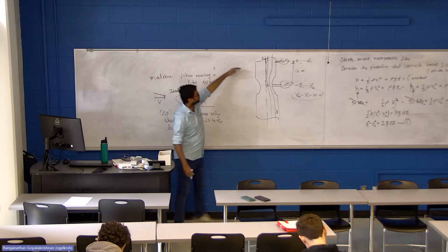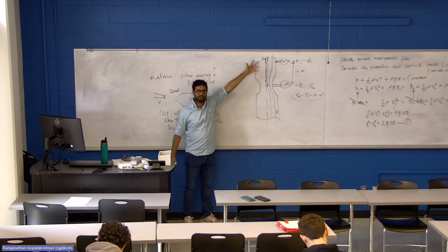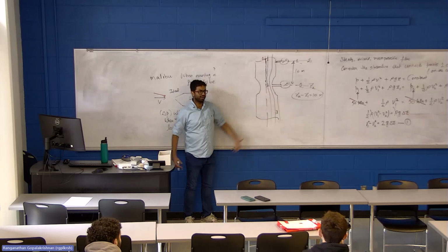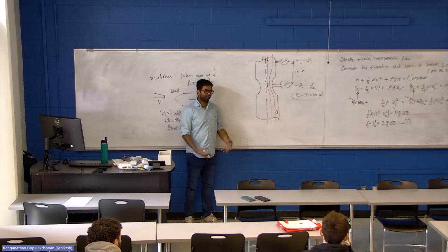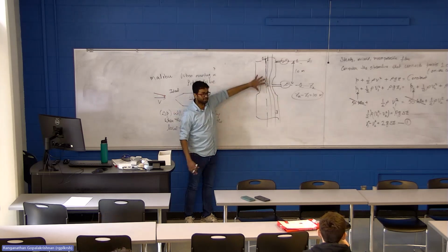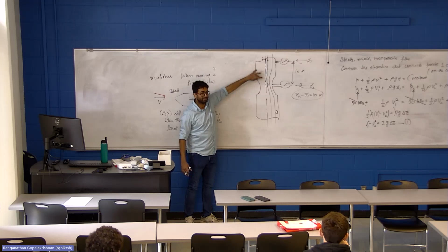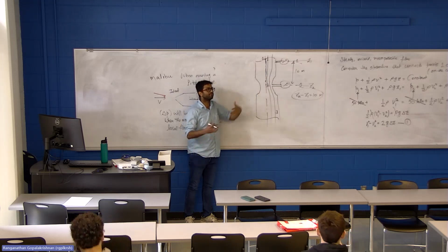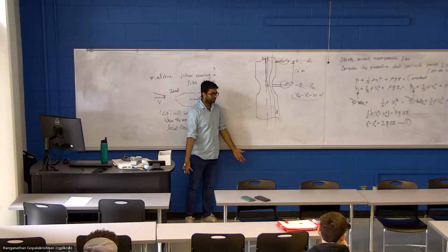The fluid has to accelerate, because if you are at a movie theater and there is just one exit and everybody is trying to leave, we are all squeezing through. So either the density accumulates there or you have to move fast out of there. Of course, this is incompressible fluid, which means the density cannot increase. So the fluid has to leave faster in order for everybody to leave.